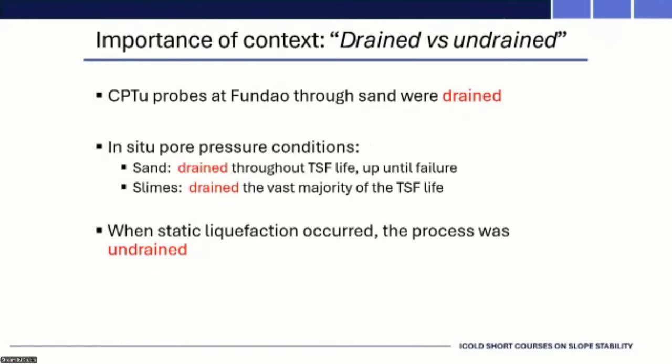Something I've mentioned before, but let's just emphasize it. The cone tests at Fundão, through the sand, that was the higher tailings, those tests were drained. And yet that material failed in undrained shearing. So, in situ, that sand was drained, probably fully drained, throughout the TSF life until it wasn't, until contraction was triggered.